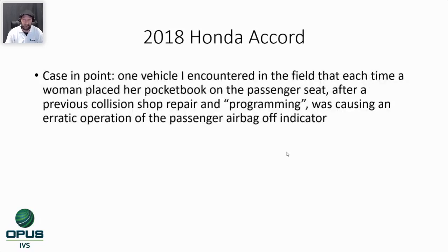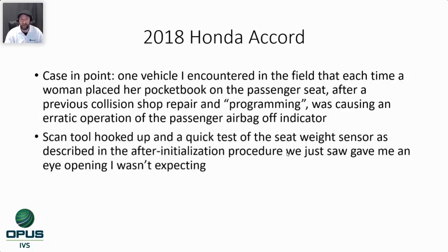Case in point, and this is more of a case study for you, but one vehicle that I encountered out in the field, each time a woman placed her pocketbook on the front passenger seat after a previous collision shop did a repair and programming, it was causing an erratic operation of the passenger side airbag off indicator. The scan tool hooked up, quick test of the seat weight sensor as described in the after initialization procedure.